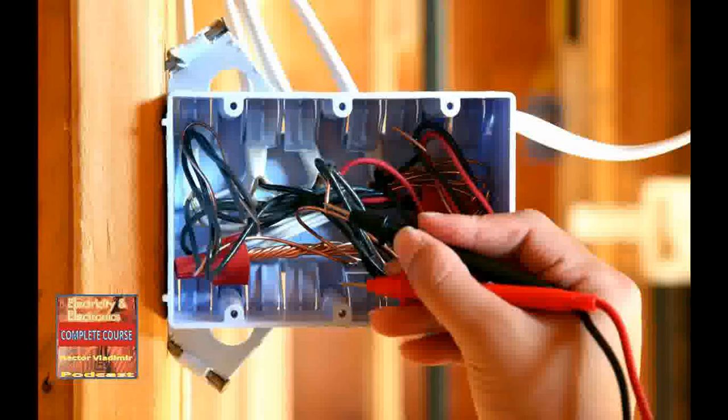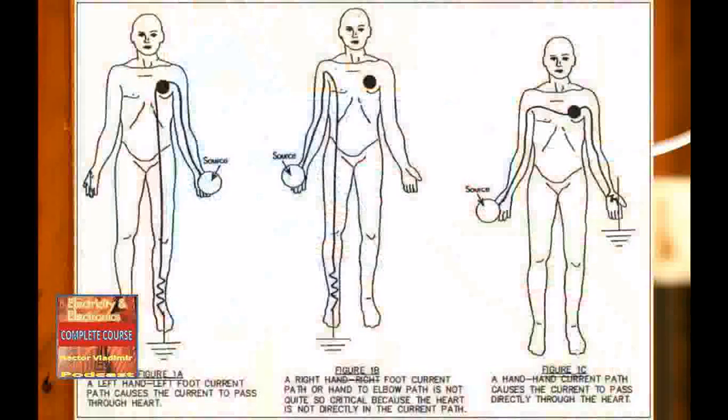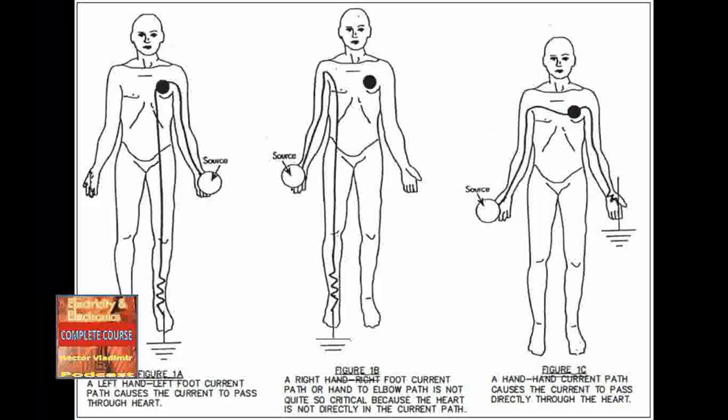Lesson in safety. One of the best ways to avoid fatal electric shock is to keep one hand in your pocket while working with high voltages. This way, any current flowing through your body does not flow through one hand and out the other. The amount of resistance through a person's body depends on many different things. For example, a resistance path from hand to foot will be higher than from hand to hand, especially if the person is wearing dry shoes in good condition.